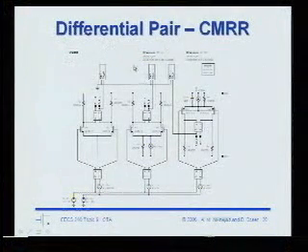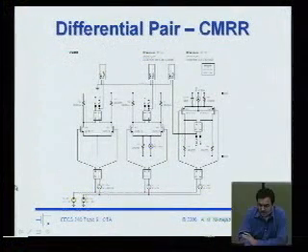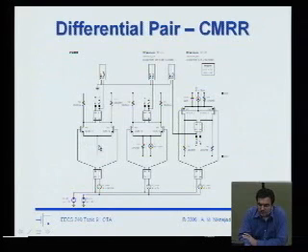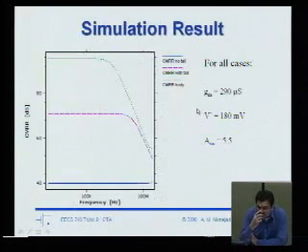And this is basically 3 SPICE experiments, if you can read it. First one is the grounded source differential pair. This one's a true differential pair with a current source. Sometimes this is called a pseudo-differential pair for the reason that it doesn't have the current source. And then finally, a PMOS differential pair where we're able to tie the body and source together. Okay? And so here's the simulation results.